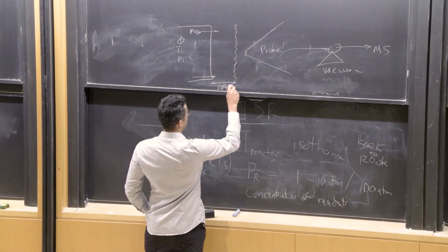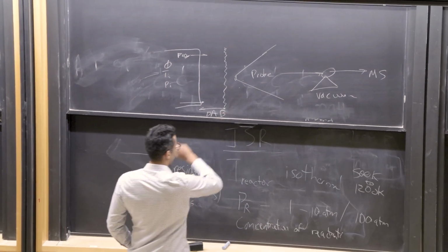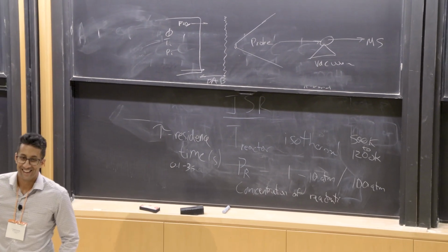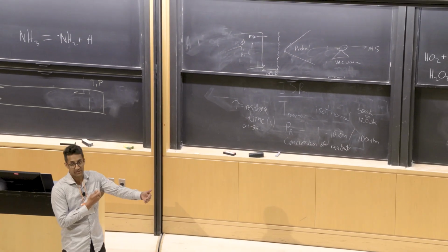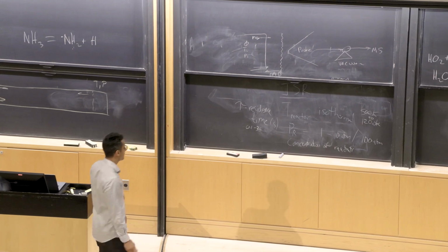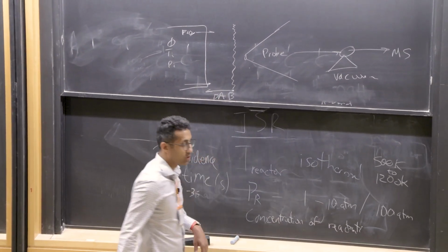distance from the burner, DAB, let's say. DAB, not dad, okay. Distance above burner, or distance away from burner. That distance increases. And also your flame thickness will be broader, okay? Your flame will be broader as you go to lower pressures.